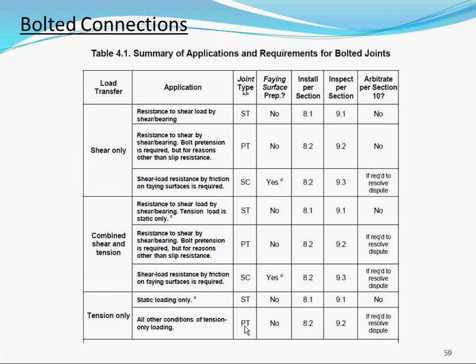However, we don't want the framers to need a tool to pretension it. So we test it as snug tight. If somebody points out, well, your load is tension only, so how come it's not static loading, you should be pretensioning, the thing is we tested it to be snug tight. And that's one condition we put in the code. We tell you what some of the exceptions in the bolting requirement are. In 341, all bolts need to be pretensioned, regardless. So for us, we put in that it be snug tight.